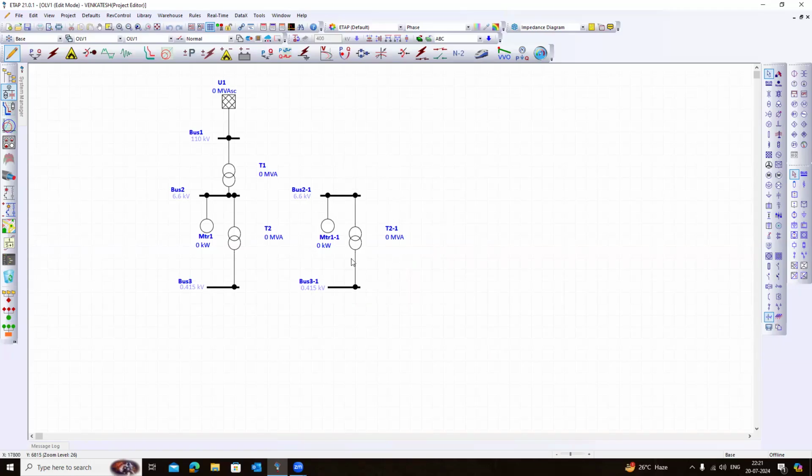If you observe here, this is control, let's select the branch, control shift and drag. So this is one method of creating the duplicate, means replica of this branch. And this is another method, through the template we are creating this, right? Now, if you see the nomenclature here, you could identify whether that element or the branch of the system is created from the template or not.